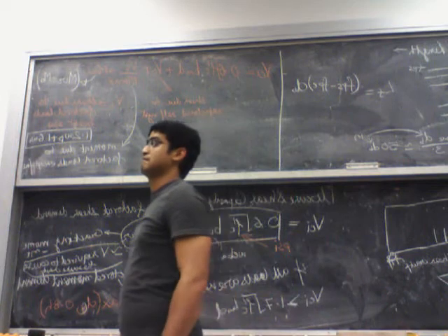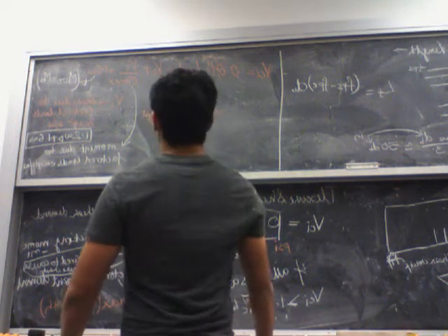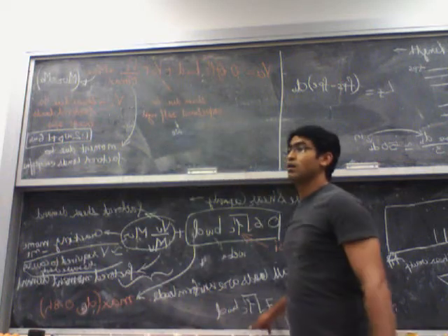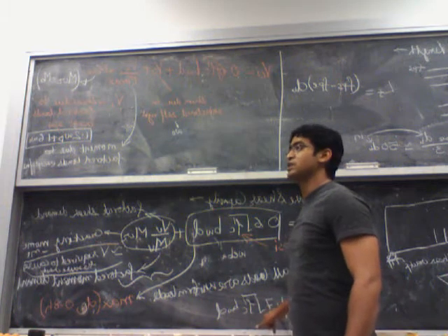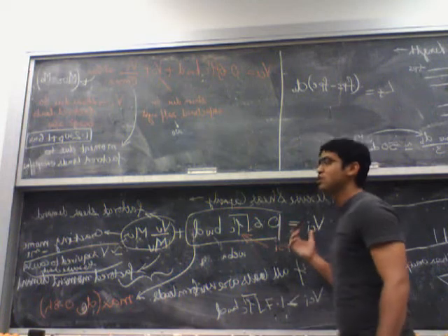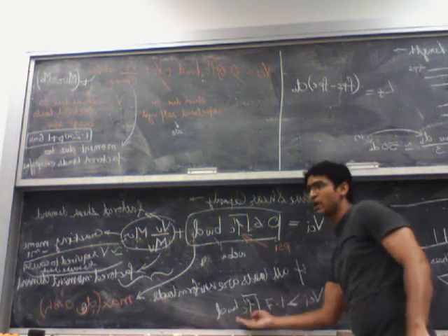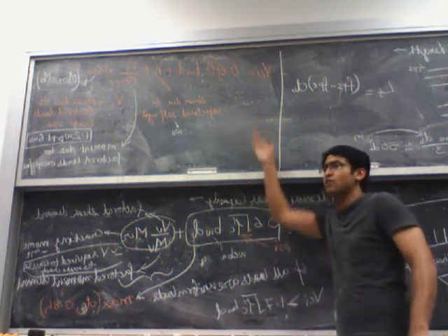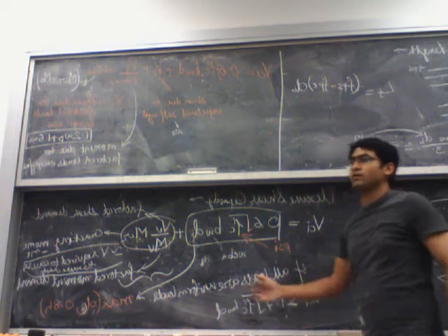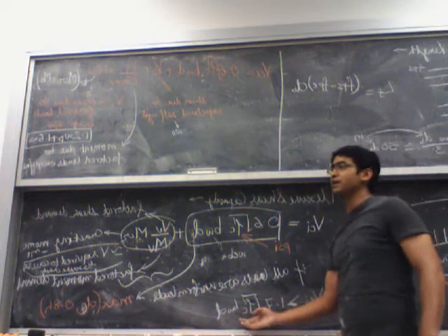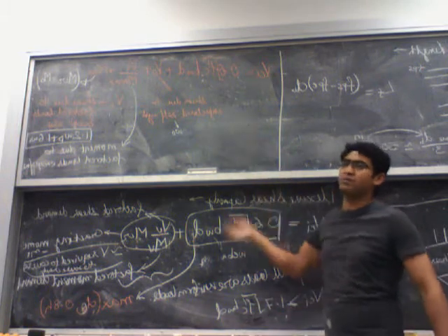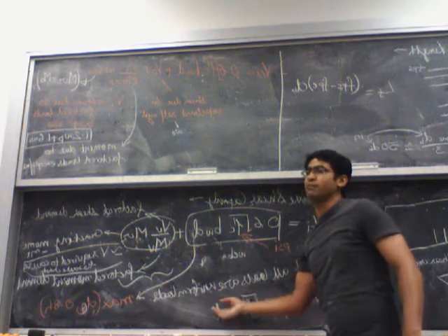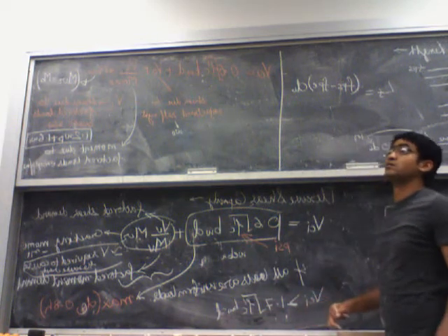That 1.7 root f prime c, is that a limit on the equation, or is that a design value? It's a limit on the equation saying that if you get a value of VCI which is less than this, you actually use this. So this is the minimum that you should get from either of these two equations. Let's say this gives you 100 kips, and depending on what kind of loads you have, the other gives you 90 kips, you actually use 100. Okay?